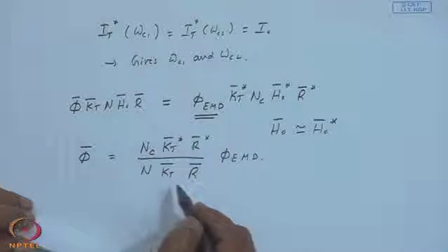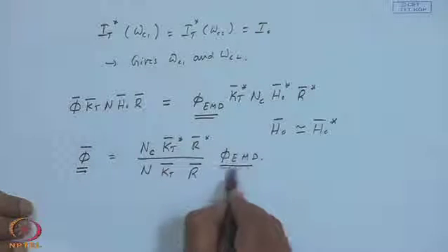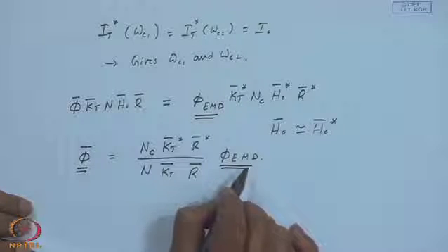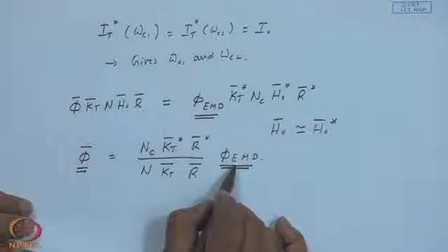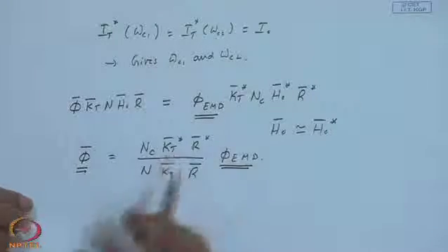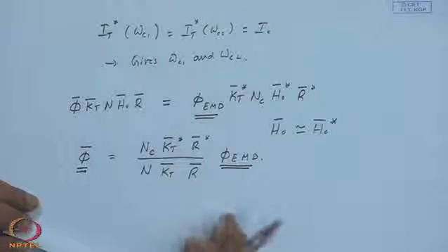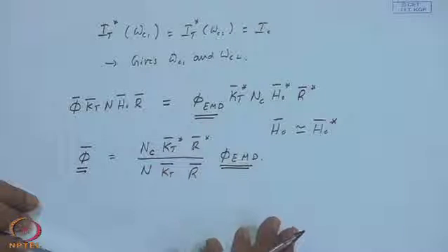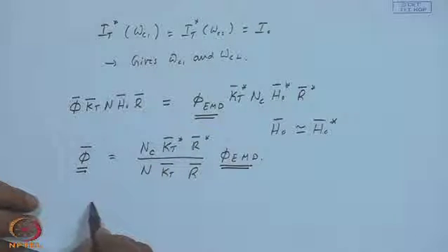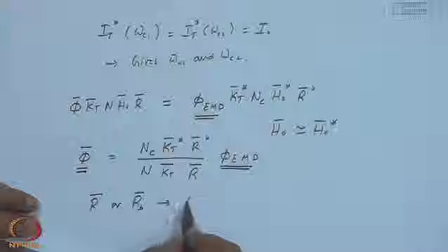So, the sum and substance is that the monthly average daily utilizability has been related to the utilizability of a single day, that single day being called the equivalent mean day. The property of this day is that the clearness indices are always above the clearness index KT minimum, and the average is KT bar star. So the question of IT minus IC being negative on any of these days does not arise. Basically, the analogy is from R bar or RB bar, where the averaging works.